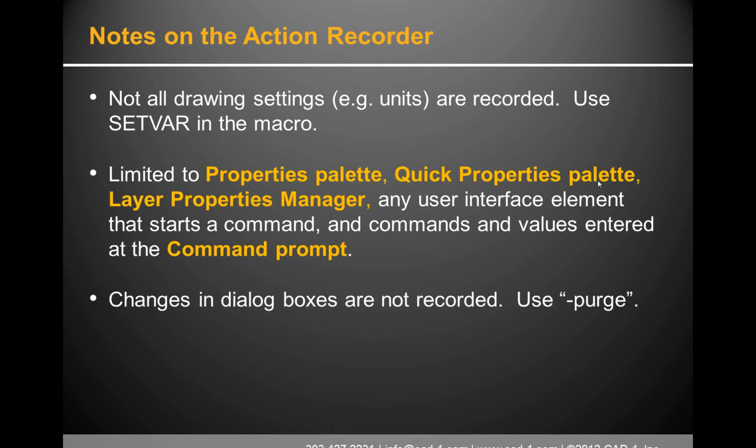Yeah, and actually what you could find is this: if you have a bunch of drawings, an example of use might be a legacy drawing made prior to the ability to create non-printing layers, and you'd like to create a viewports layer in there and set it to non-print, non-plotting.